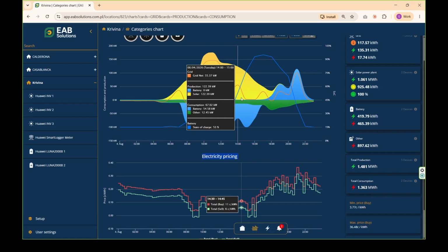It can perfectly well happen that the internet works, but what fails is the battery. If the battery failed, it's very rare, but it can happen that for a day or two the battery fails because of some problem or other. In that case, nothing would happen. The PV keeps producing, the solar energy keeps being supplied to the client. If the battery can't capture that PV surplus, we'd lose two things. The surplus solar energy couldn't be stored, because we have no battery. And arbitrage couldn't be done, because we have no battery, so those two levers would be temporarily disabled.